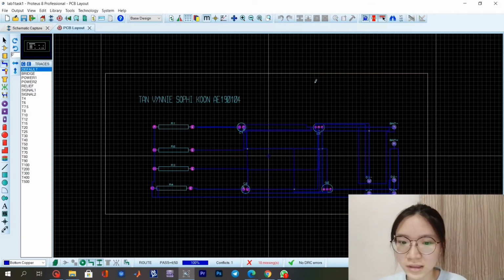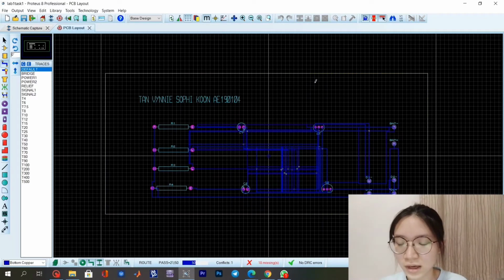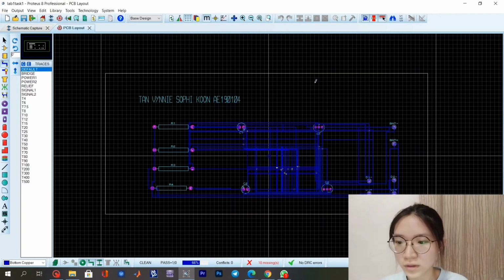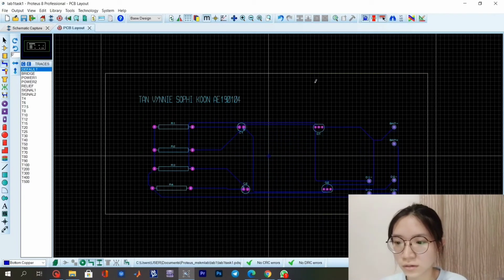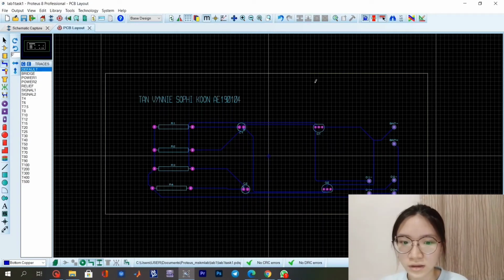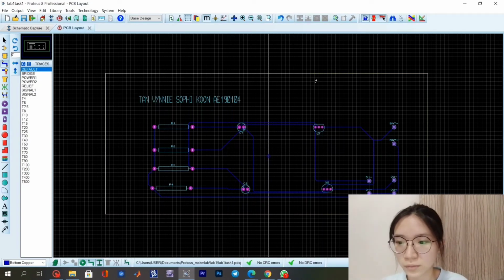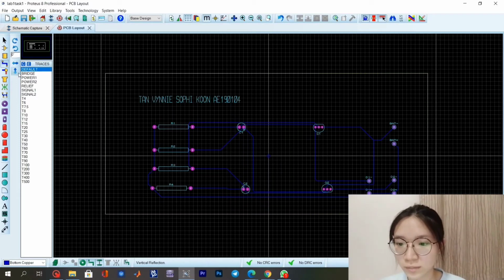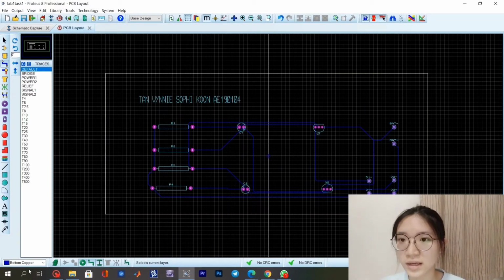This is an intensive calculation process and we need to wait a few seconds, then the circuit will automatically route. So okay, the bottom tracks are shown by the blue line, and we need to make sure that the circuit does not have any additional green line. If in this case, the circuit must be reloaded. So here is the circuit after routing, and that's all from my part.